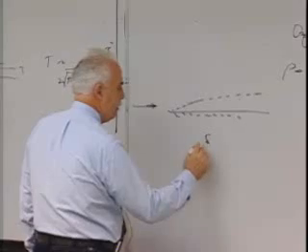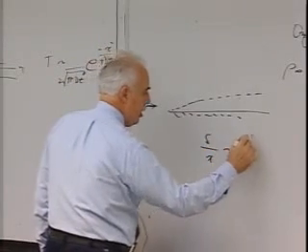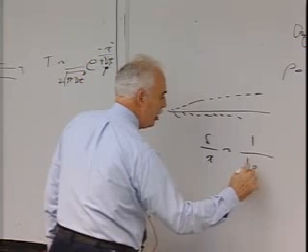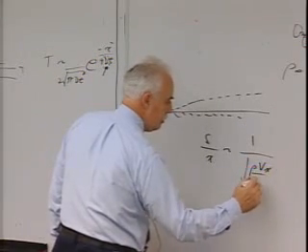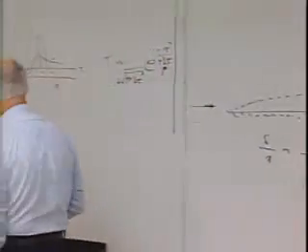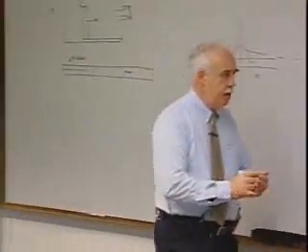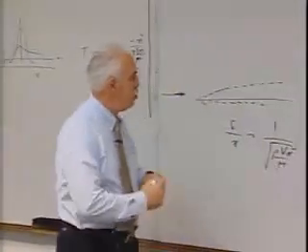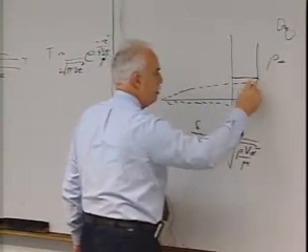The boundary layer compared to x varies as 1 over square root of Reynolds number. Where does that come from? Same diffusion. It's a diffusion of the shear of this wall against the undisturbed flow.